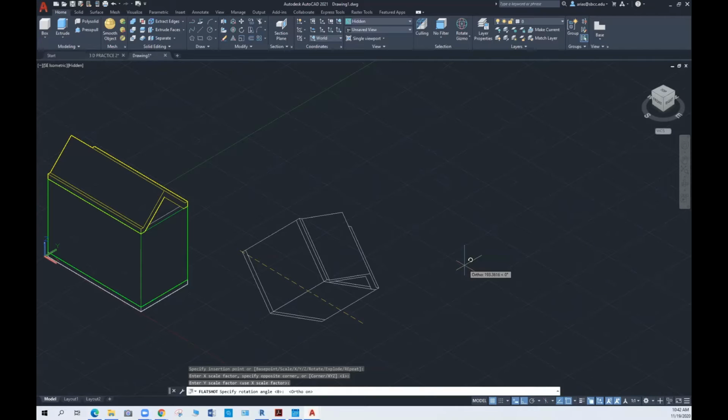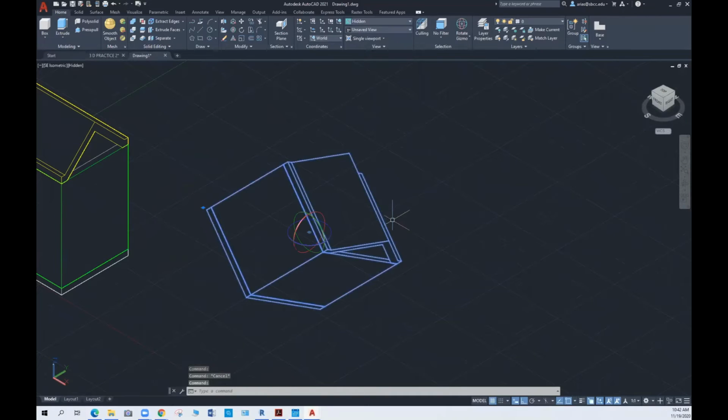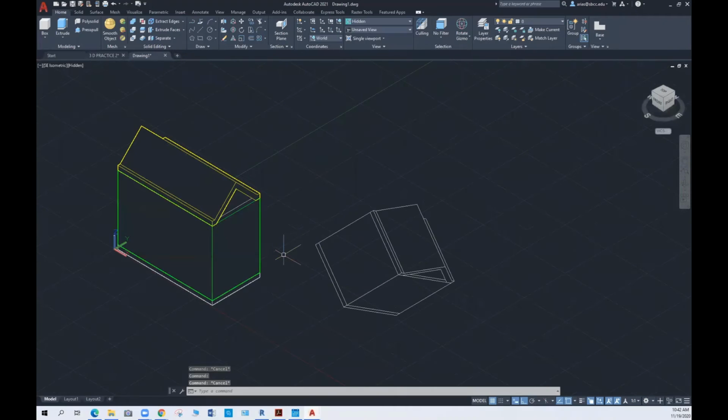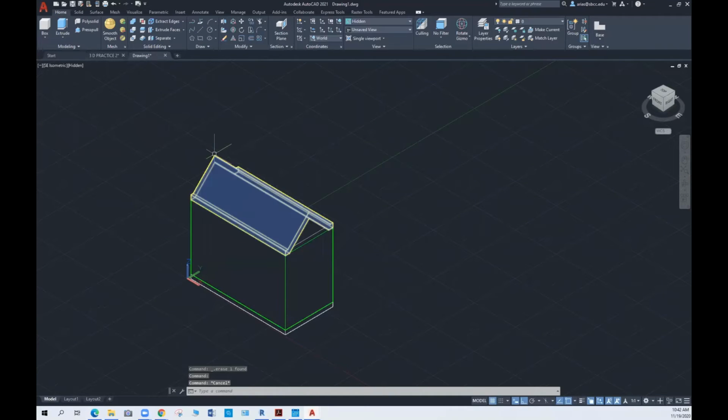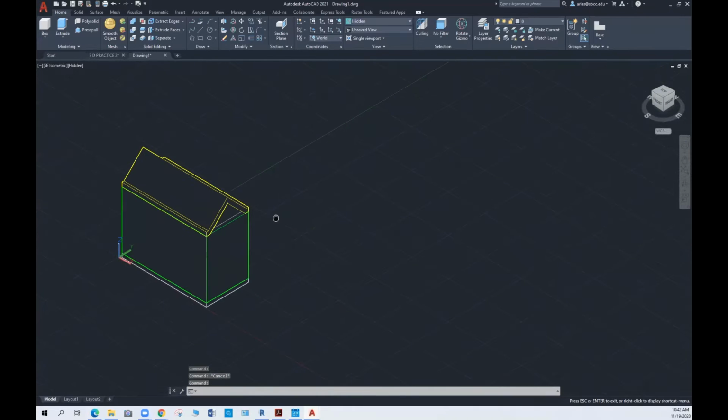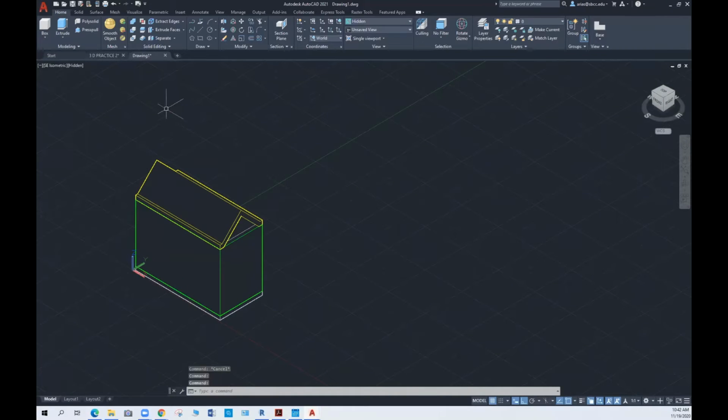So flat shot, ortho on, enter scale factor, rotation angle, and let's say 0, and done. And so what I have here is a view of this object. It's not what I want really, because what I want is exactly this, but as a flat shot, because a flat shot allows you to see this with just the edges. So that's the idea, right?